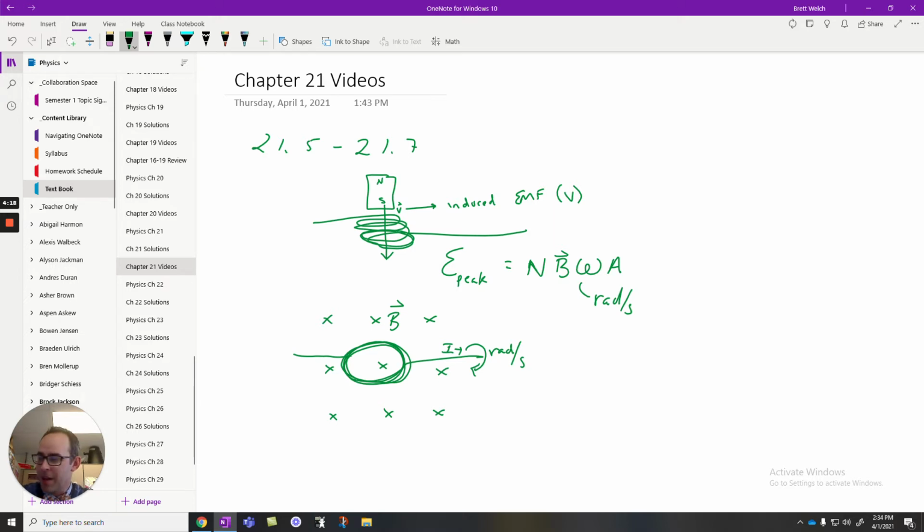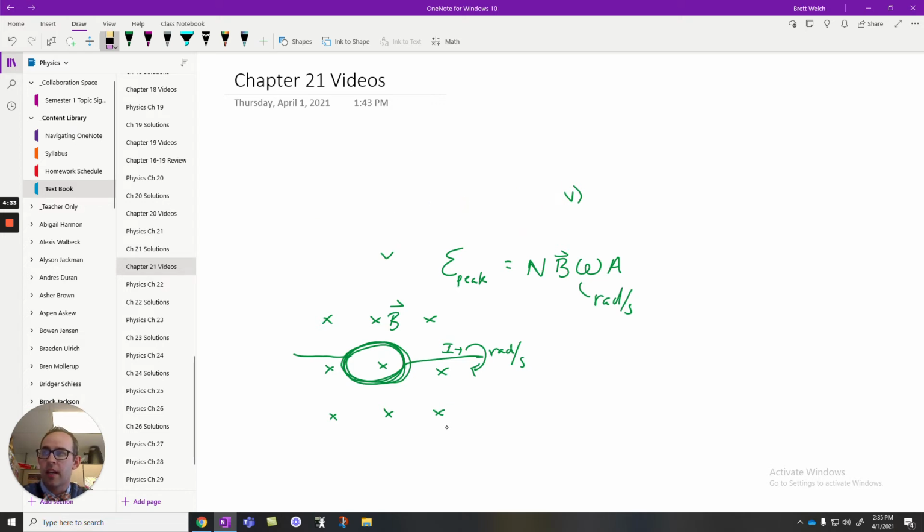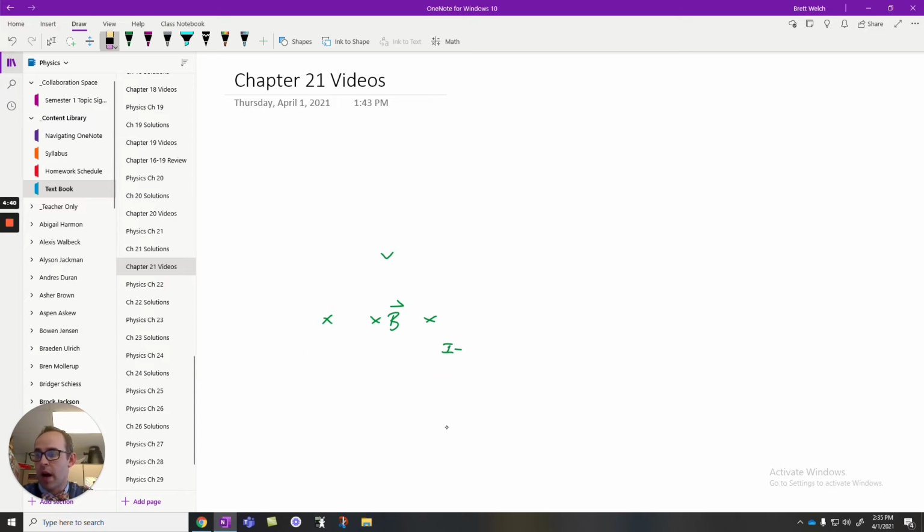But let's remember, if you make a big circle, it's going to have more torque on it. It's going to be heavier. It's going to be a lot of things that we may not want. So there are always trade-offs in producing or inducing a current. All right, so there's our basic initial idea that we can induce a current by changing the magnetic field that goes through the wire. It's really important we understand that it has to be changing. If it's stagnant, then we don't induce a current.